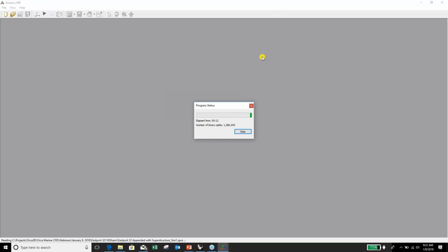propulsor driving the force. In the resistance run that we did earlier, you can think of that as a towed simulation. The target velocity will automatically be reached, and as much force as necessary will be produced to generate that target velocity. Whereas in a self-propelled run, you only have the propulsive forces accelerating the vessel, so it typically takes longer to get up to the speed of the analysis. Okay. So in a minute here, it'll finish meshing and we'll see the same model, but with propulsors in it.